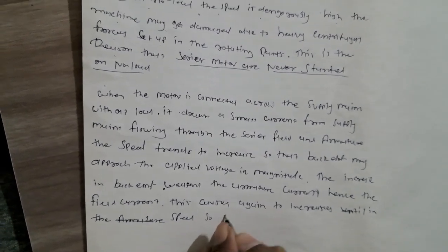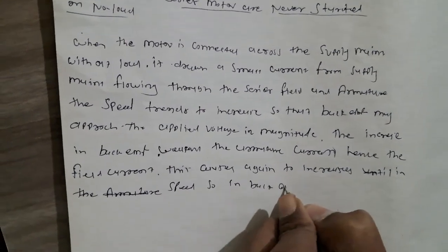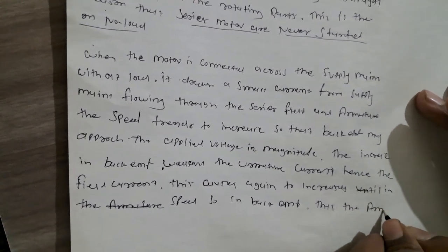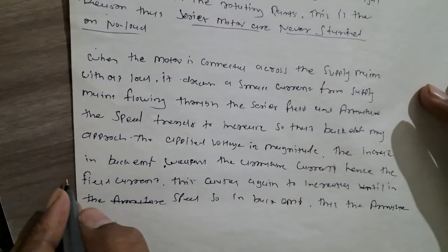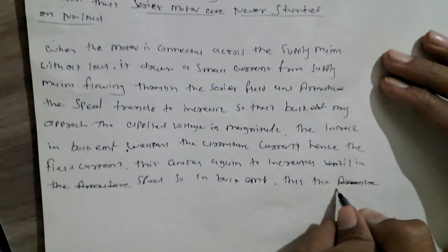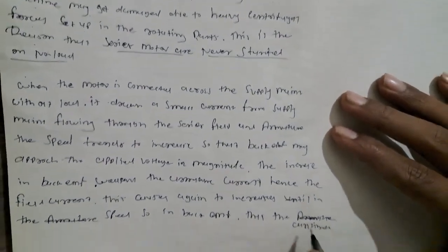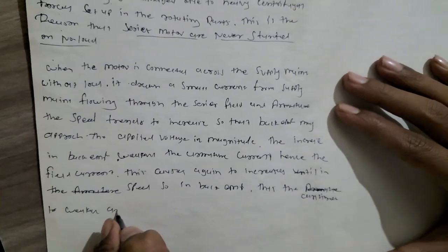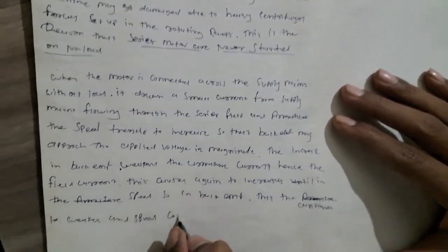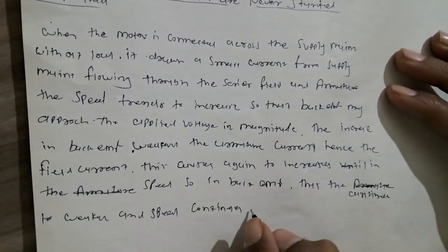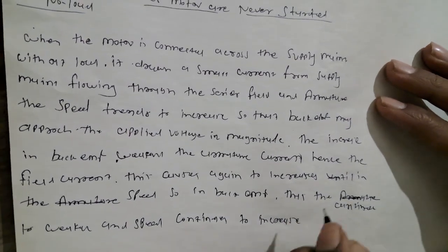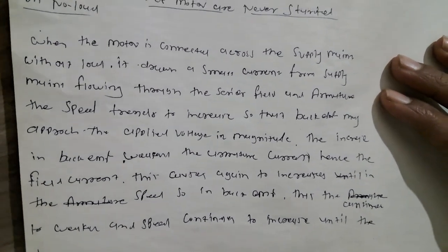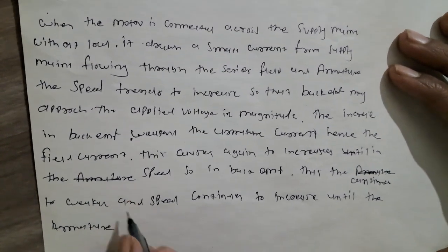Thus the field continues to weaken and speed continues to increase until the armature gets damaged.